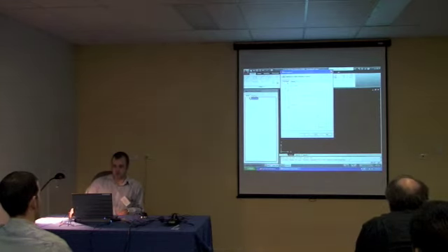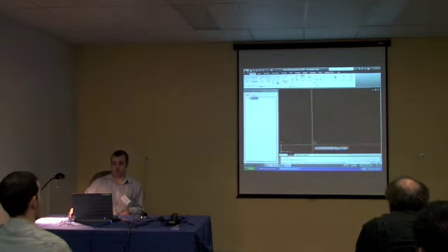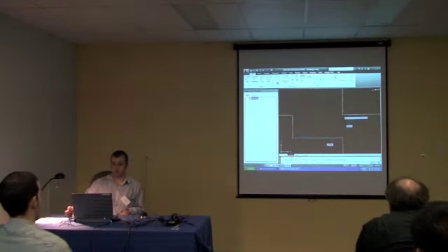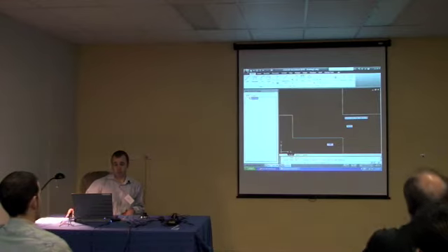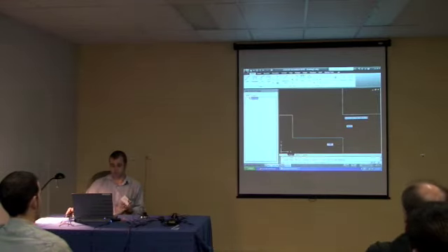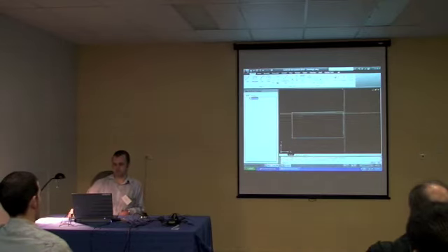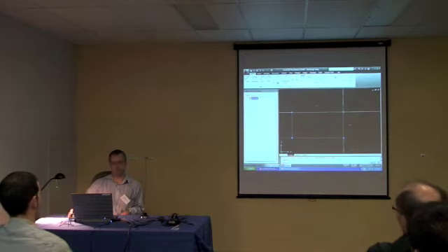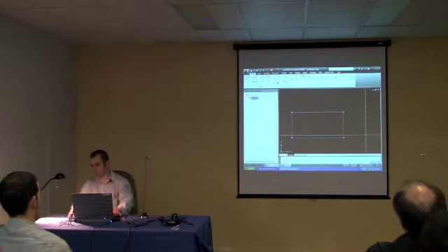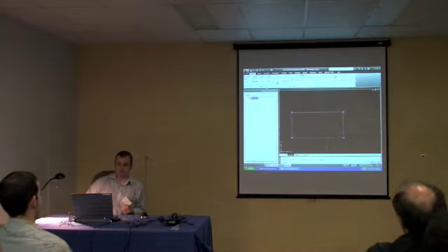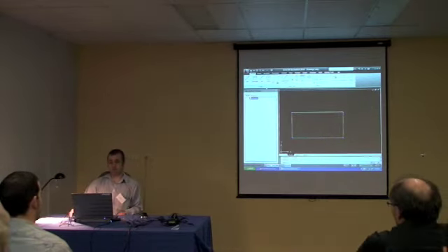So, the midpoint of the base and the top corner. With dynamic input turned on, which was introduced a few releases ago, you can type these dimensions straight in. So 400, tab, 400. So I have an 800 by 400 rectangle. As I said, there are lots of ways of generating those. You guys will be using mechanical and can play with that.